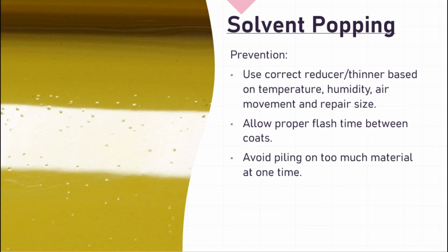To prevent solvent popping, you can use the correct reducer or thinner based on temperature, humidity, air movement, and repair size. Allow proper flash time between coats. Avoid piling on too much material at one time.